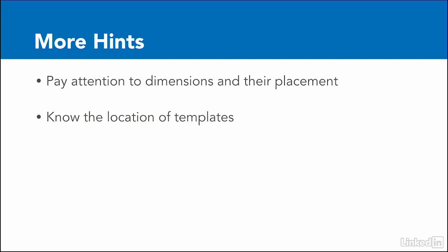My other recommendation is to use the measure tool after you've created your part, measure it, and make sure it does match the inputs from the testing client. Sometimes you can easily make a mistake by using a material going the wrong direction or a flange going a different direction or something like that. When you're creating a part, it's easy to make a mistake and just have your part grow a little bit bigger or be a little bit smaller than you're expecting. So definitely doing a quick measurement check on the outside of a part will definitely be worth your while.